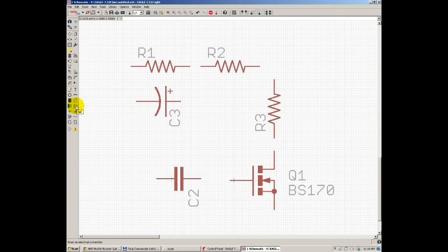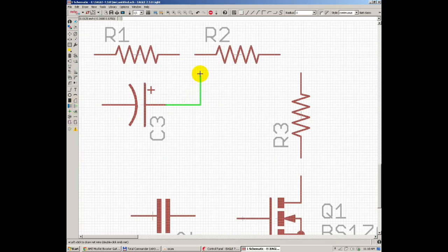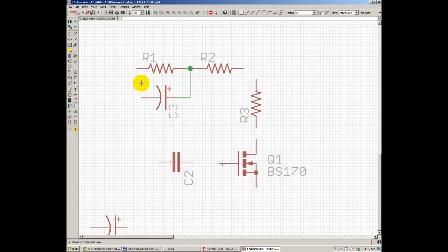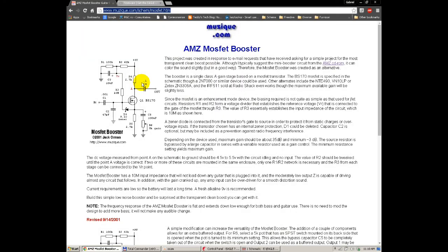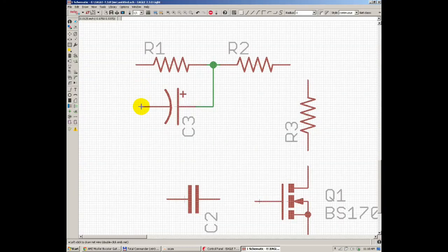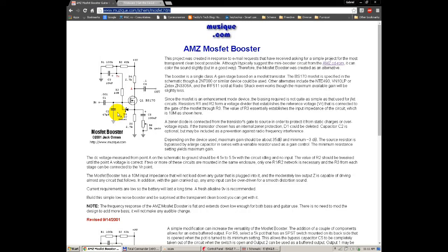There is a big difference between the net and wire. Wire is just a simple wire, while the net command will enable you to actually connect the parts. If you use the wire command, your parts will not be connected. The wire command is just a graphical one. You can always use Ctrl-Z to undo your actions.